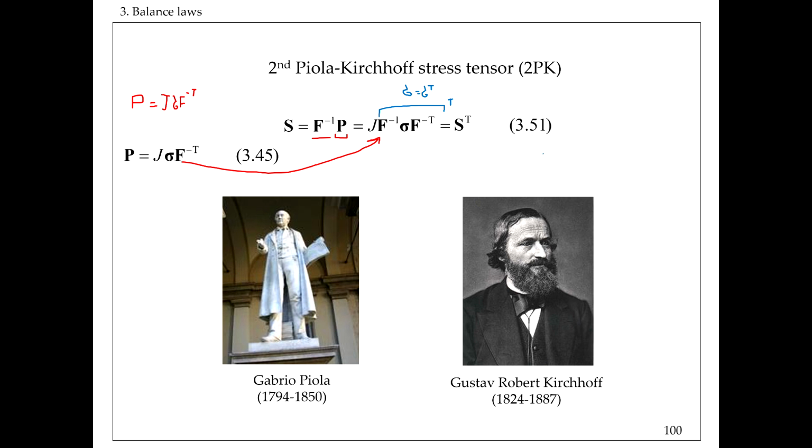Now, finally, we are going to complete this by defining our boundary conditions again. We have all the balance laws, which are differential equations, so we can find a solution for that, but to fully solve the problem we also need to satisfy the boundary conditions, which again can be defined through the traction, calculated in the undeformed configuration.